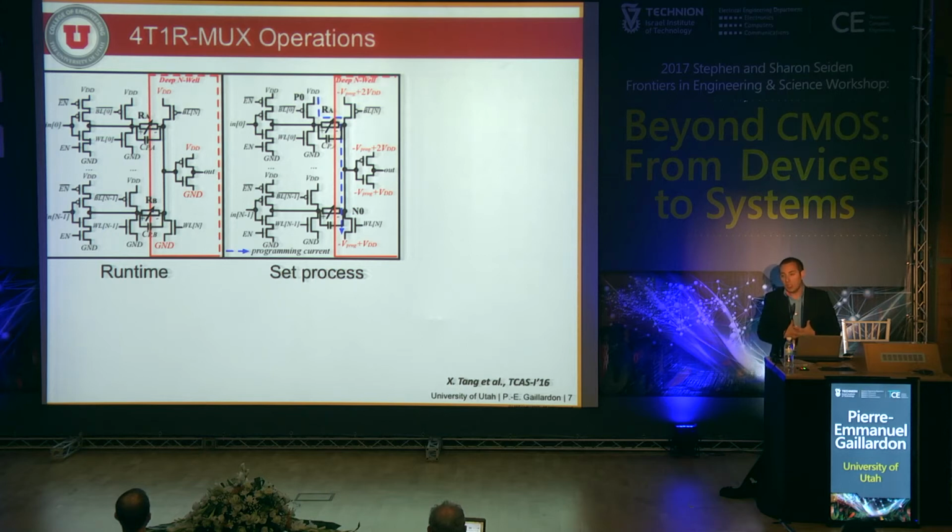So what is interesting here is that we'll be able to program a memory with a Vprog equal to twice the nominal voltage of our transistors without risking any breakdown for this technology. So this is quite interesting here because we don't need to use I/O transistors to program the RRAMs, and that gets very interesting for logic, when we use both RRAM and regular transistor in the same architecture, we don't pay too much price in simply programming this structure.